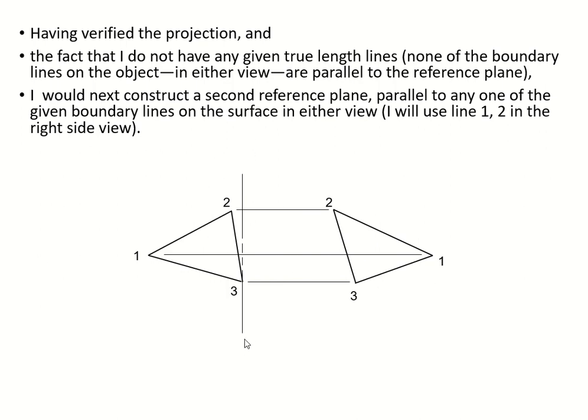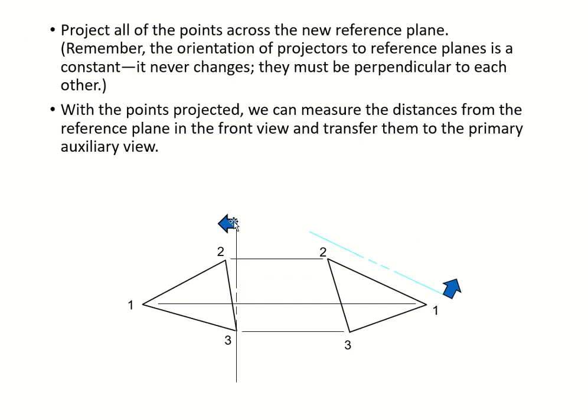And then we're gonna throw this full line, but this time just throw it at the edge of this front view, okay? Because why do we do it? Because you need to project this thing to the next view. So therefore we have to measure the distance in between these points. So therefore we usually use this approach by sticking this full line to the edge of it. Okay, we'll go that way for dimensioning.